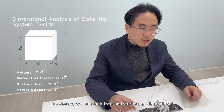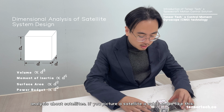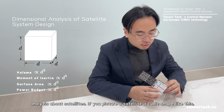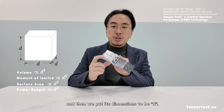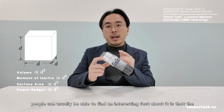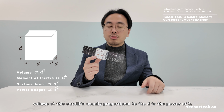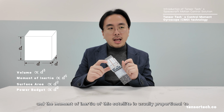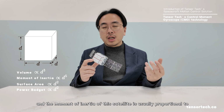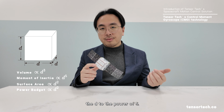Firstly, we can look into an interesting dimensional analysis about satellites. If you picture the satellite as a cubic shape like this, and we put its dimension to be d, then people can usually find that the volume of these satellites is proportional to d to the power of 3, and the moment of inertia of these satellites is proportional to d to the power of 5.